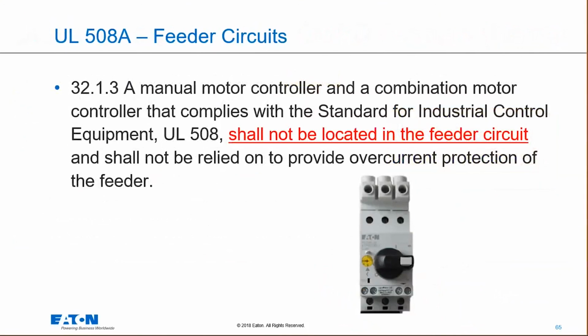So a manual motor controller and a combination motor controller that complies with the standard for industrial control equipment shall not be located in the feeder circuit. So I kind of spelled it out, but they cannot be used in that feeder circuit. So just be aware.